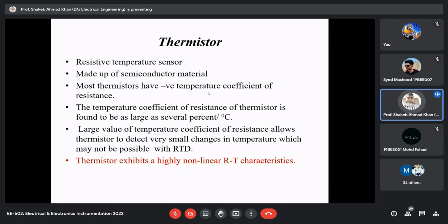So in the case of conducting material, a lot of free electrons are always available for the electrical conductivity. But in case of semiconducting material, it is controlled. So as far as its behavior with respect to temperature is concerned, when we heat up the semiconducting material, the electrons which are available in the valence band gain energy from the supplied thermal energy, cross the band gap, and go into the conduction band.